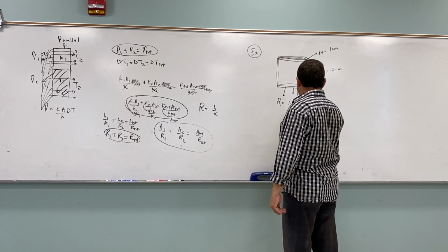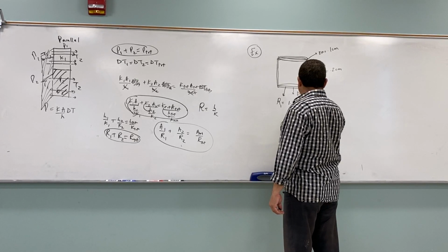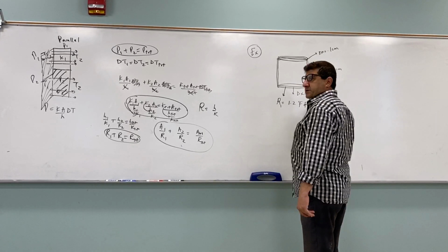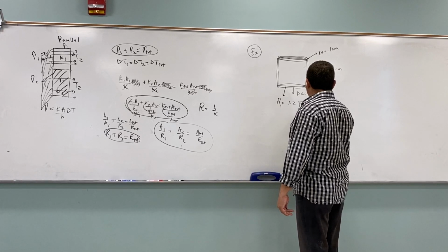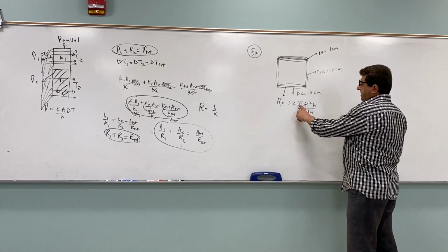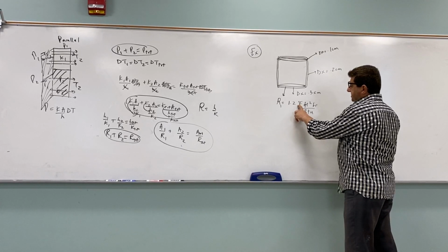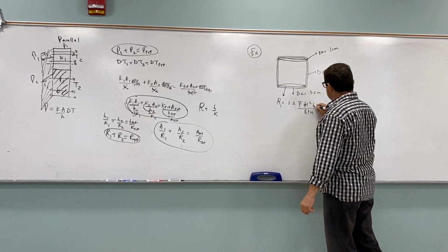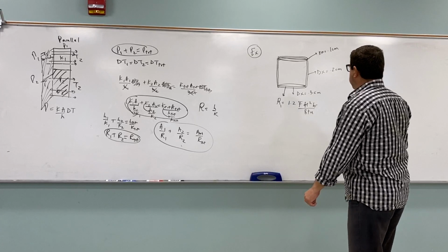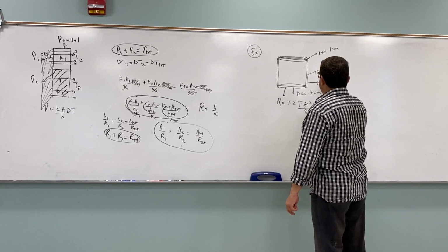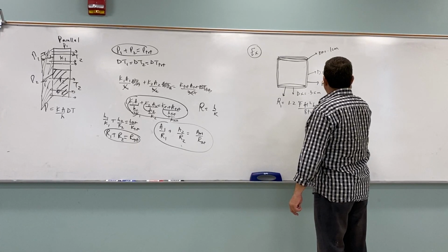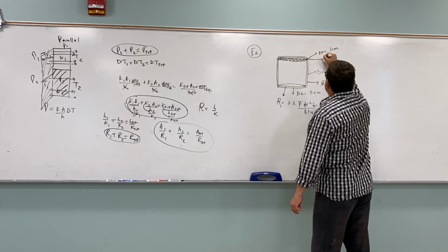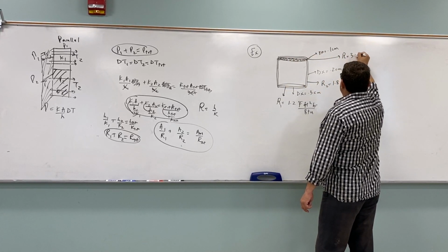And the units would be Fahrenheit feet squared hour over BTU. In other words, how much Fahrenheit difference does it take for 1 BTU to go through 1 foot squared every hour, right? And then this one, let's say, has an R value of 1.8, and then let's say the top is a better insulator, R value is 3.0.